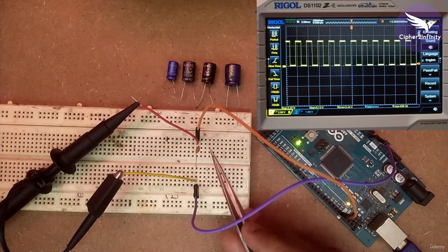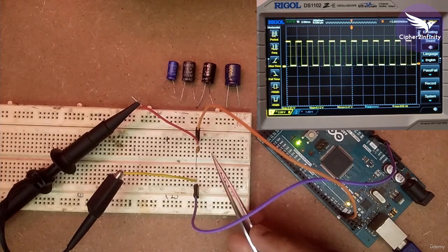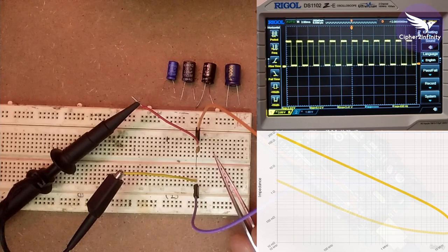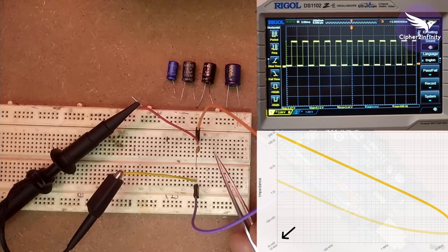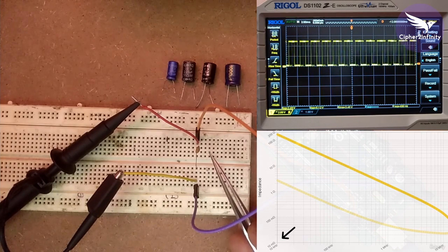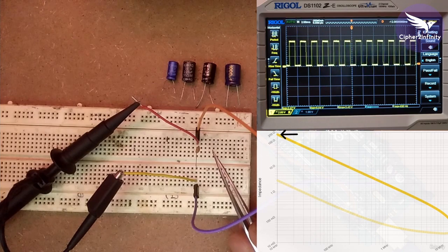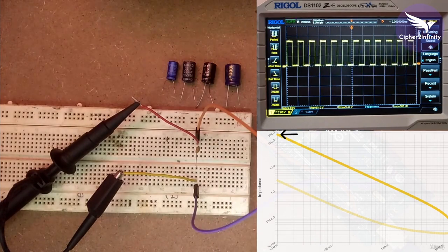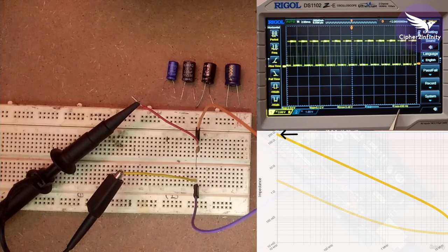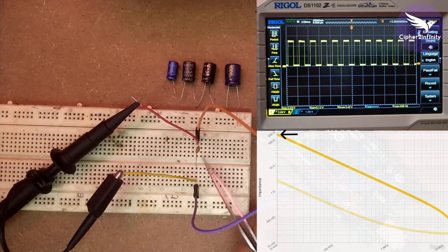So that's the reason this signal is not bypassed by this particular capacitor. When I explained the impedance versus frequency plot of the 100 nanofarad capacitor, I showed you that at 10 kilohertz, this particular capacitor was providing an impedance of 200 ohms. Now we are actually dealing with a frequency of 500 Hz. It means that this capacitor is going to provide even more impedance.